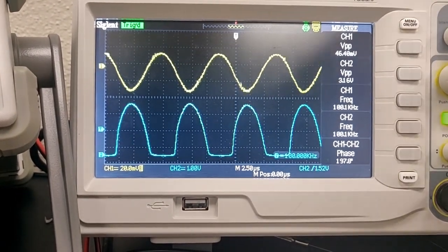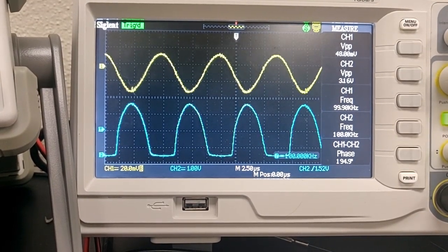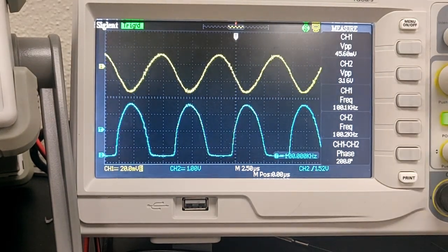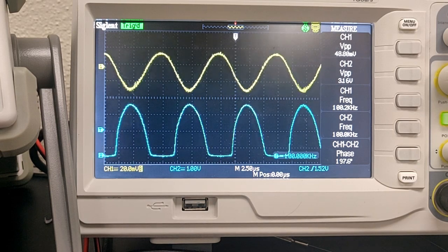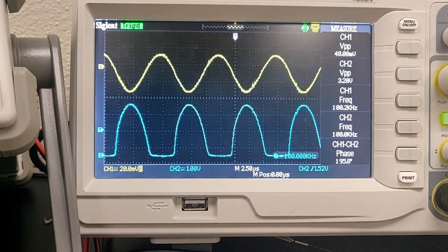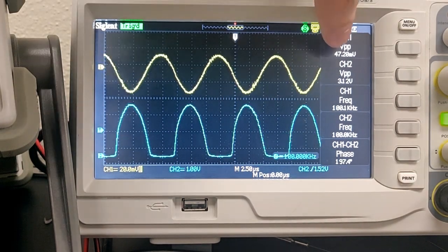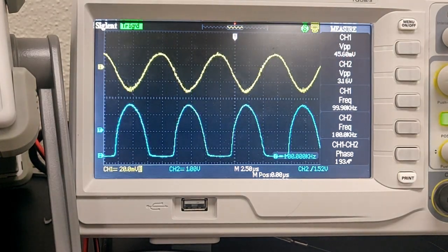And then our V out is our amplified signal, which is sort of half cut off because it's reaching the bounds of our 9-volt DC window. But that won't really matter, especially when we get to the part of actually demodulating. We can see that it is amplified. It's around 3.2 volts peak to peak.